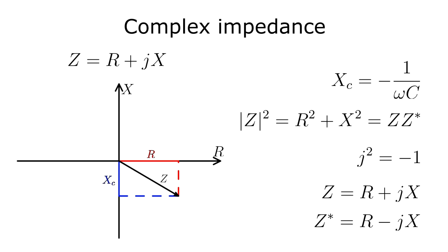The complex impedance of the circuit, consisting of resistance and reactance elements, is a complex number Z equal to R plus jX, where j is the square root of -1. The visual representation of complex impedance is a vector with the x-coordinate corresponding to resistance and the y-coordinate corresponding to reactance. The complex impedance of the circuit from the experiment can be visualized on a diagram. Since complex impedance is a vector, not a scalar, we need an abstraction that allows us to use 2D vectors as scalars. This abstraction is provided by a complex number.